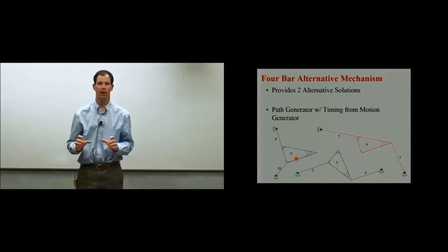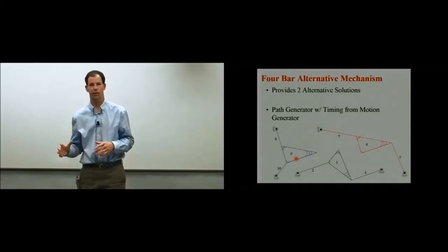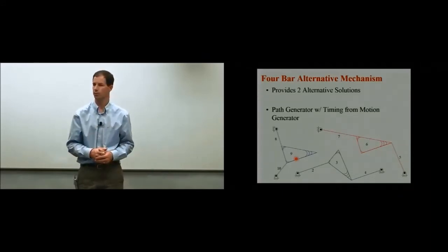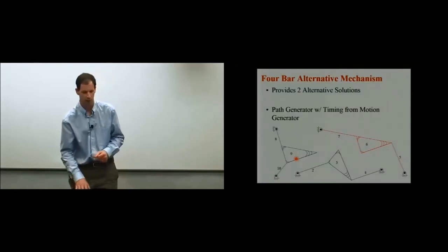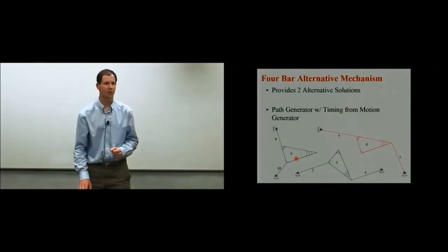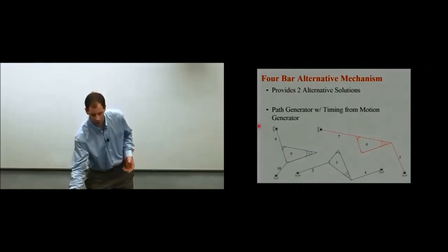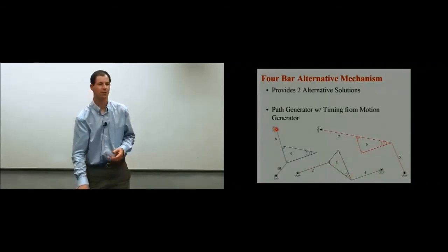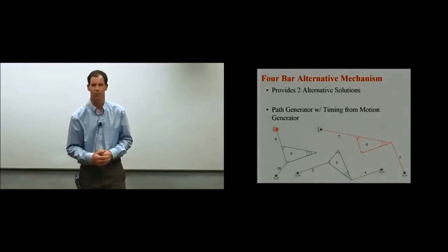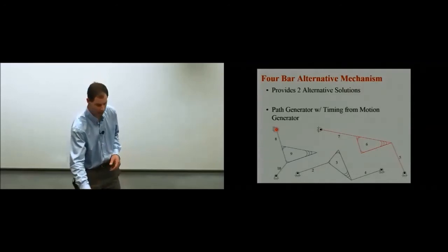But again, recognize that these couplers do not have the same rotation angles, but I can use the fact that one of my input links will have the same rotation as one of the couplers. So this is another way to apply it. A little bit challenging, because the problem with this cognate construction is that when you synthesize the base 4 bar, you really don't know where that ground pivot is going to end up yet. So you could end up with a pretty poor solution and done a lot of work to get there. But this is the way that it has been used in the past.